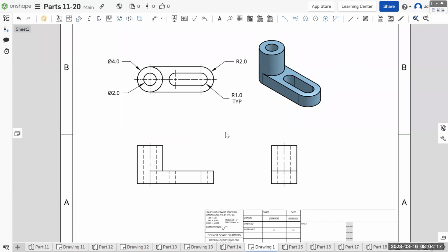All right. Then we just need location in both directions, which, when you're ever dimensioning things about curved surfaces, you always dimension where it looks curved or curved edges. And because we don't really have a left edge to start from, like we have in the other parts, we are going to use this as our anchor point to all of the other dimensions. As long as we locate them from a similar point, we'll know where they are.